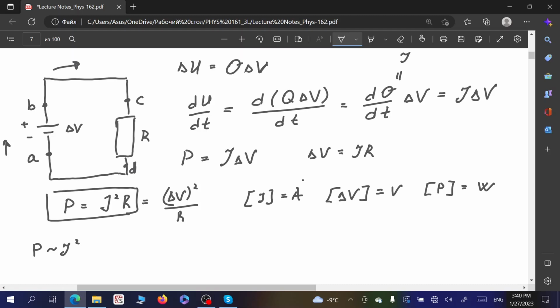So that is quite a complicated system. Obviously, it would be better to transport power without changing the voltage. However, there is a fundamental reason why this has to be done, because electric power dissipating over a resistor is proportional to electric current in second power.